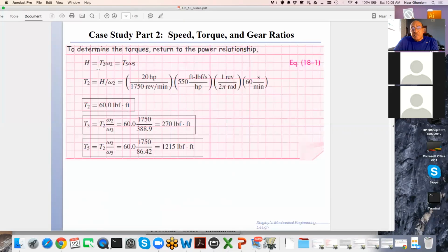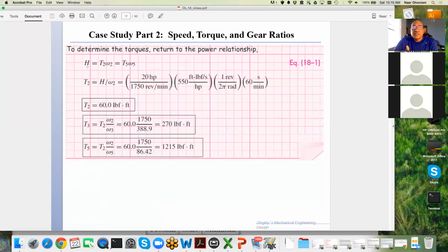So H is constant. If you have an efficiency, because you lose some of the horsepower in friction and in irreversible heat loss and so forth, there's usually an efficiency of, say, 0.75, 0.8. So that needs to be determined from measurements, usually measurements or experience.